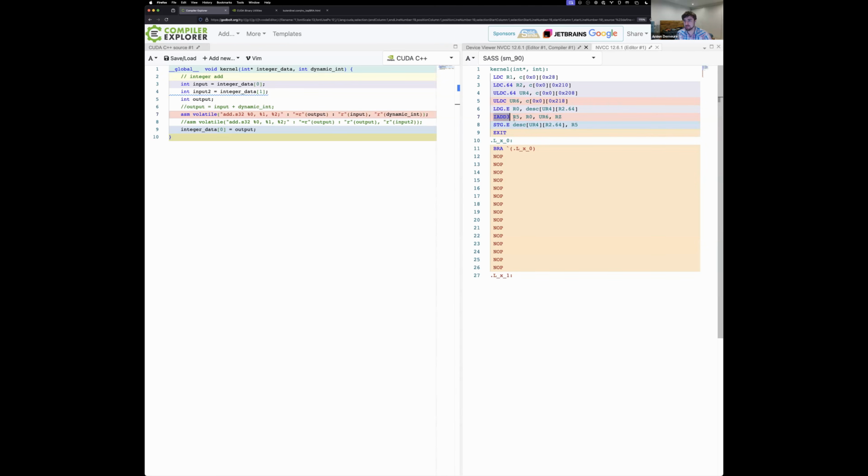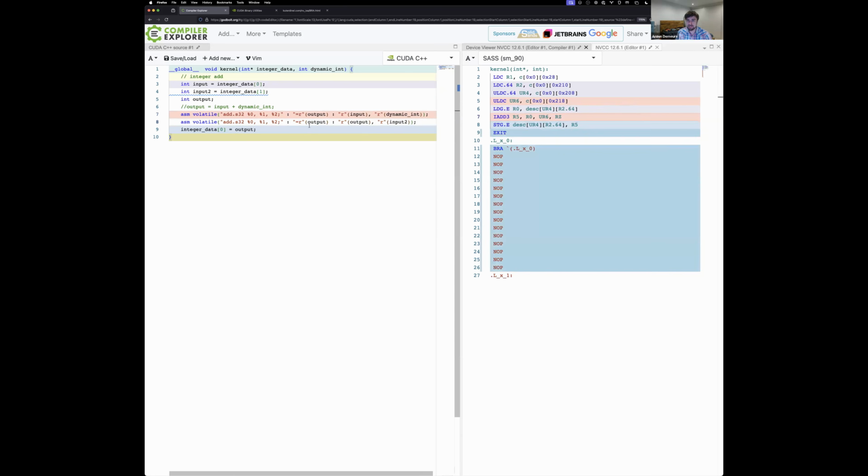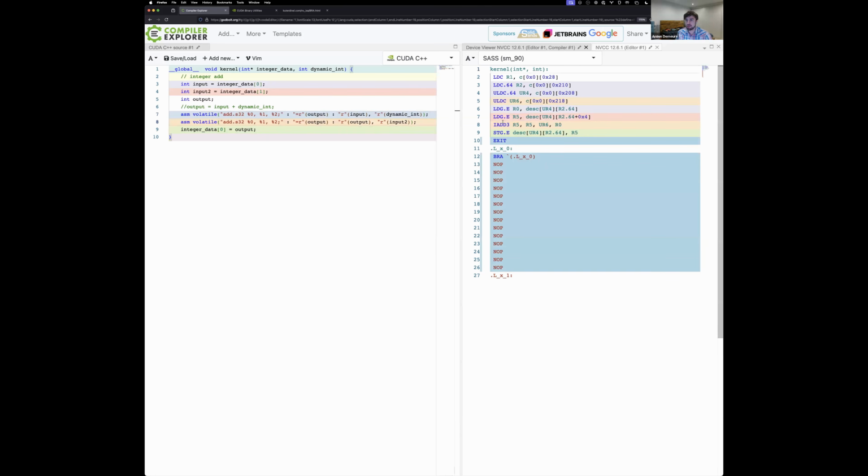What this does is write to R5, adding R0 and uniform register 6, and then this input is not used. Now, if I increment the next line, that's a second addition with another input. I've got another load, but I don't actually have an extra addition instruction. I'm just reusing that empty operand that was not used previously.